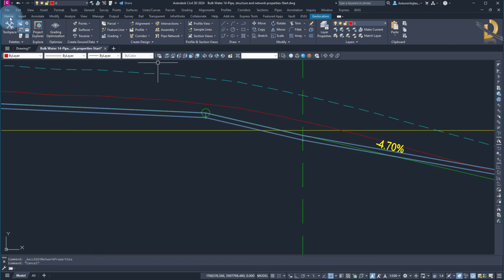If you go to ribbon home, and then under the pipe network, we have a pipe network creation tools or create pipe network from objects. But then we also have a pressure network creation tools. Those are different network types. Those were actually developed for water networks. And really the visual appearance is better. But again, the functionality is still very poor and doesn't provide everything we need.